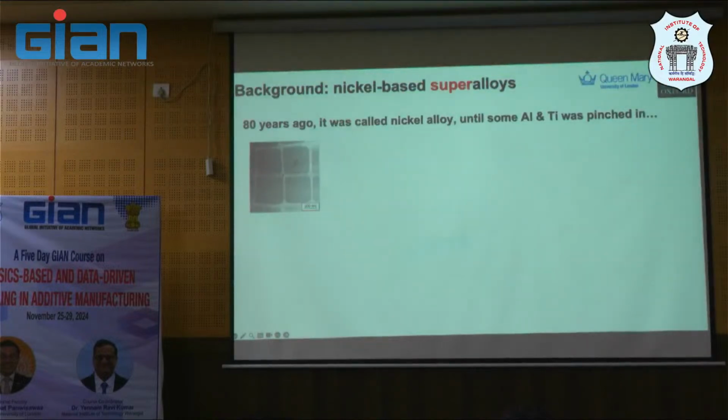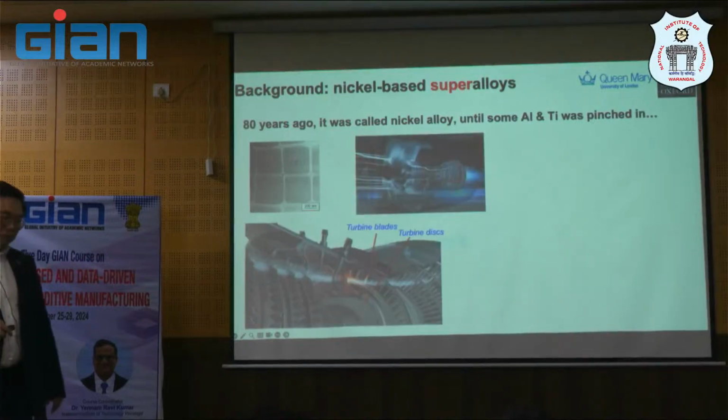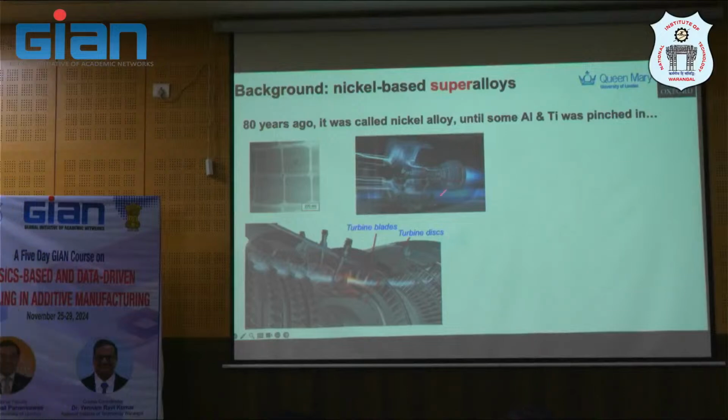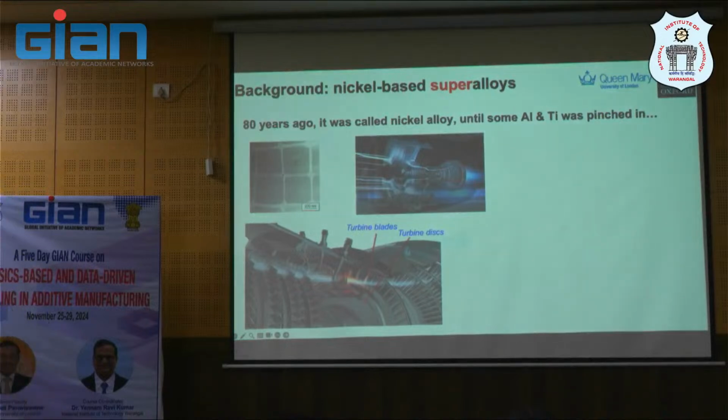And then, as you know, if we keep this in mind, in order to develop a new composition, we need to look back a little bit at what we need. This composition is supposed to be used in high temperature applications. As we all know, this is for high temperature. When I say high temperature, it's performed at least above 850 degrees centigrade, or above 1000 degrees centigrade. And we're focusing on critical parts like disc or blade material. If not a single crystal blade, it will be some other blade made from Inconel 718.